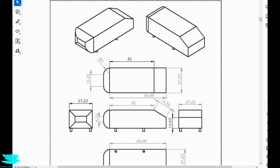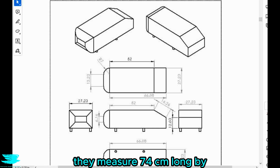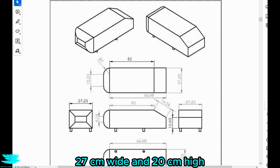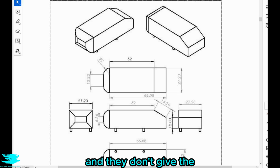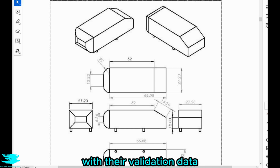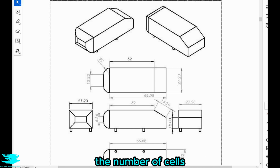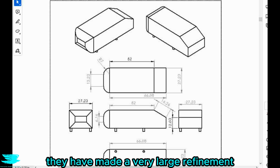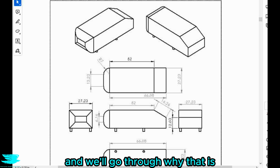Now with this CFD, they didn't exactly overcome the size difficulty because these armored bodies aren't full-size cars. They measure 74 centimeters long by 27 centimeters wide and 20 centimeters high, so about 1 to 7 scale models. They don't give the exact reason why they chose a scale model, and also why about 1 to 7 in the ratio, but I imagine it has to do with their validation data, which we'll get to in a little bit, and also potentially conserving the number of cells they need. As we'll also see later on, they have made very large refinement regions to accommodate this overtaking maneuver, and we'll go through why that is.